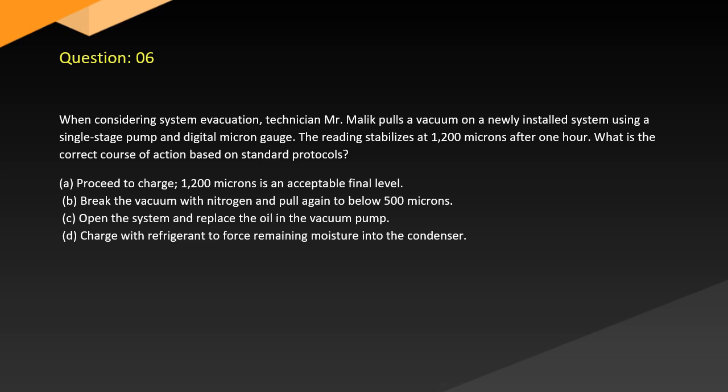Question 6. When considering system evacuation, technician Mr. Malik pulls a vacuum on a newly installed system using a single-stage pump and digital micron gauge. The reading stabilizes at 1200 microns after 1 hour. What is the correct course of action based on standard protocols?